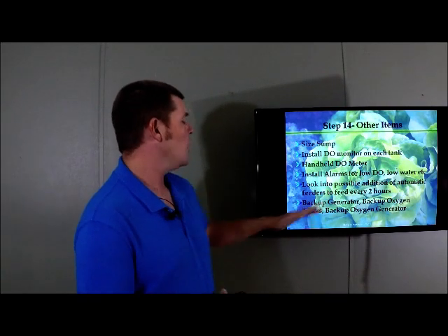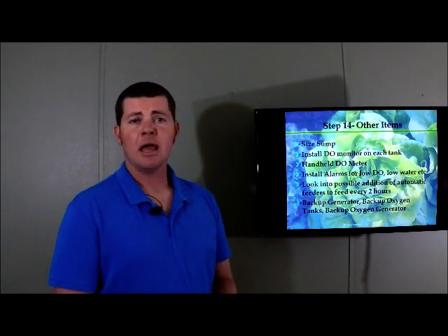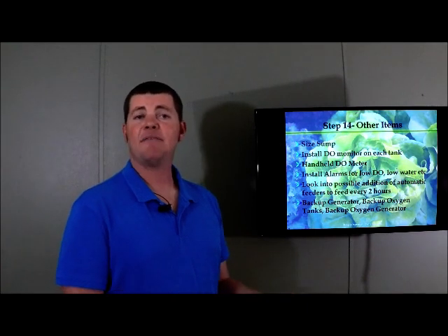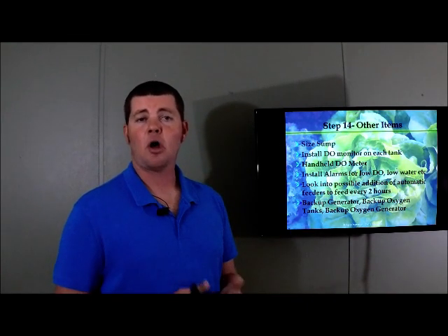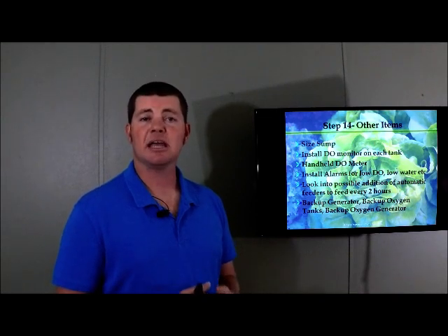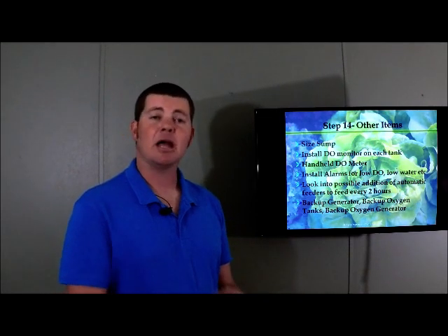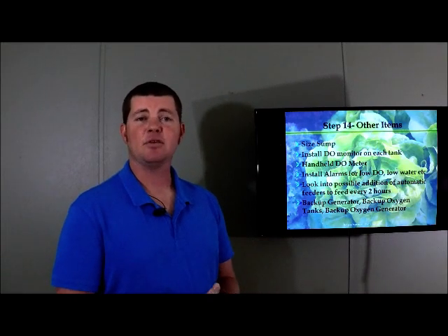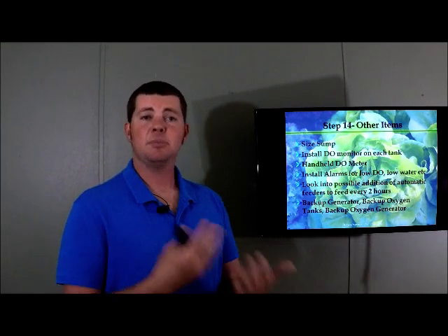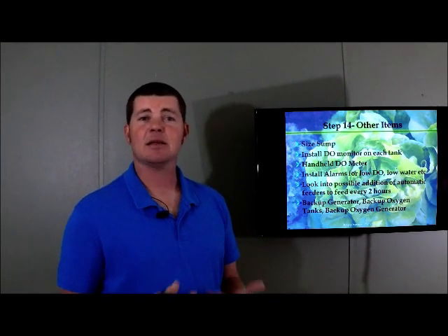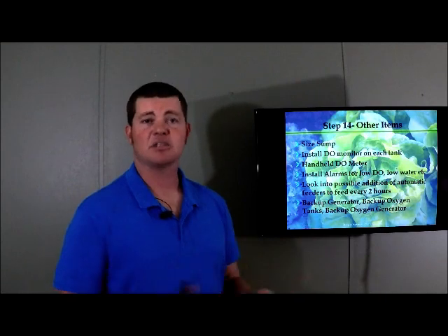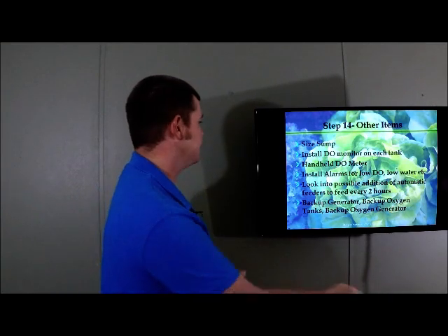You could also not use an oxygen generator and talk to a liquid oxygen supply company, have them deliver and install an on-site liquid oxygen tank that has positive pressure, and you would pull directly from that. You would size that tank based off of your monthly oxygen needs, and it would be refilled just like a propane tank or a natural gas tank is refilled by a service company on a contract basis.